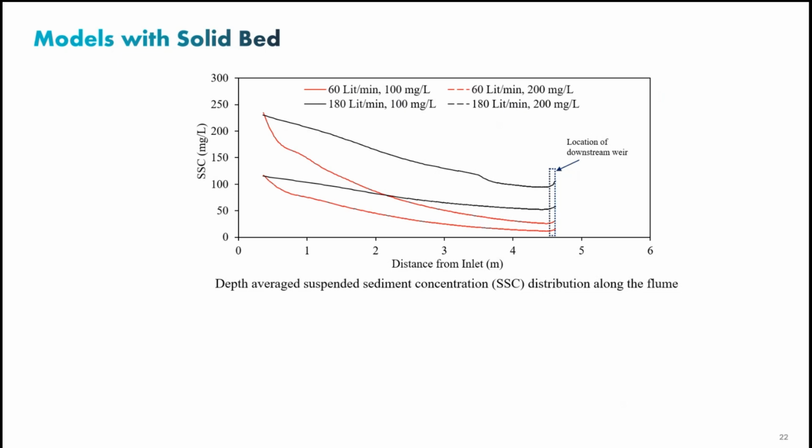As you can see, with the smaller flow rate, you get higher efficiency. Starting from 200, you go all the way to, let's say, 100. It's about 50 to 60%. And then from 100, you go all the way to 60, 40%. So the numerical model replicated what we saw in the lab, with the same exponential trend in sediment removal throughout the system. Next slide, please.